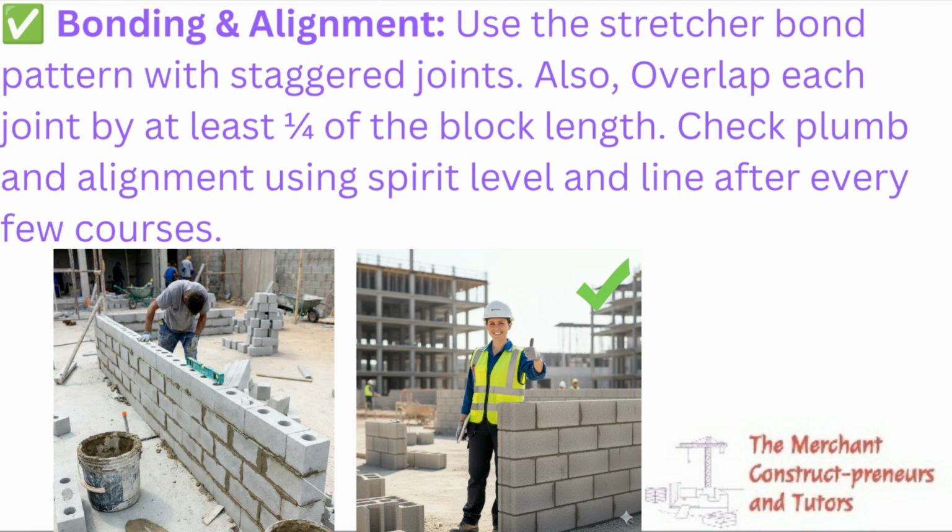So another thing is bonding and alignment. Now look at the images. You can see the way the walls are aligned. They are not stacked just vertically. The lines or the joints are overlapping, and that's the stretcher bond that we're using there.